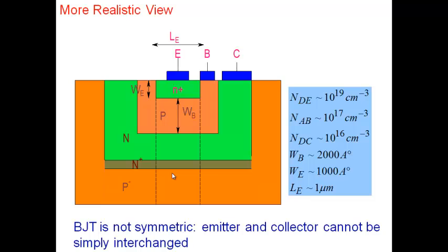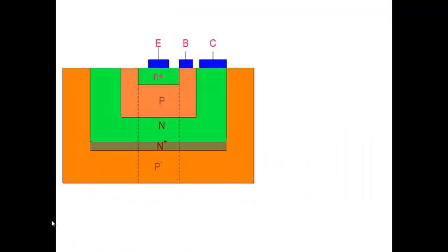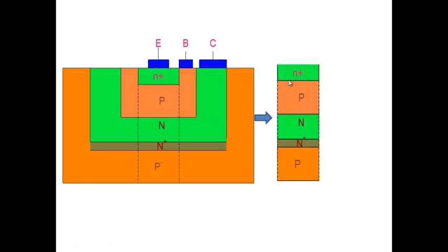So when I talk about bipolar transistor, note what I'm talking about. I'm taking a cross section, a part here in between these 2 dotted lines, and this is what I'm drawing. So when I draw a simplified schematic of NPN, what I'm doing is I'm taking this particular part. This is where most of the action takes place. The bipolar action, the transistor action takes place here. The rest of the regions are for making contact. So this is where the bipolar transistor is. And so in a simplified form, this is what we get here.